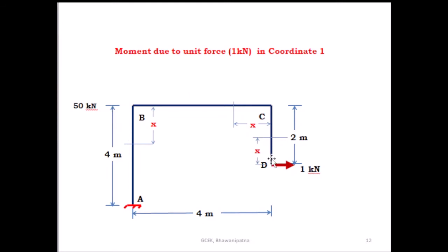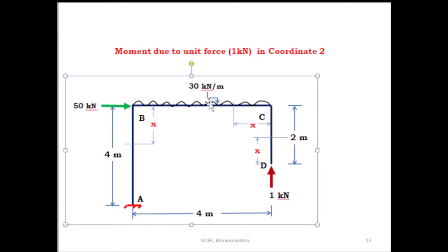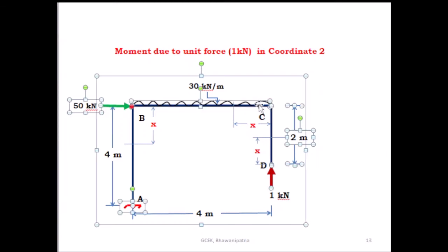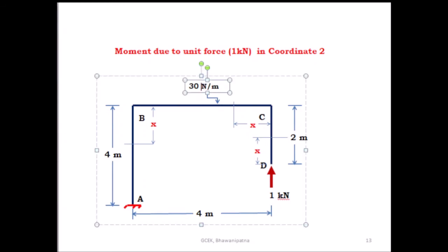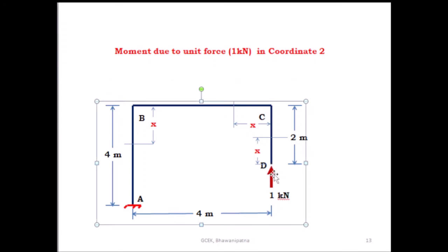Then apply a unit vertical force at D and remove all the external loading. Only take the unit vertical force. Due to this unit vertical force, find out what is the moment here, and what is the moment here, and what is the moment here.